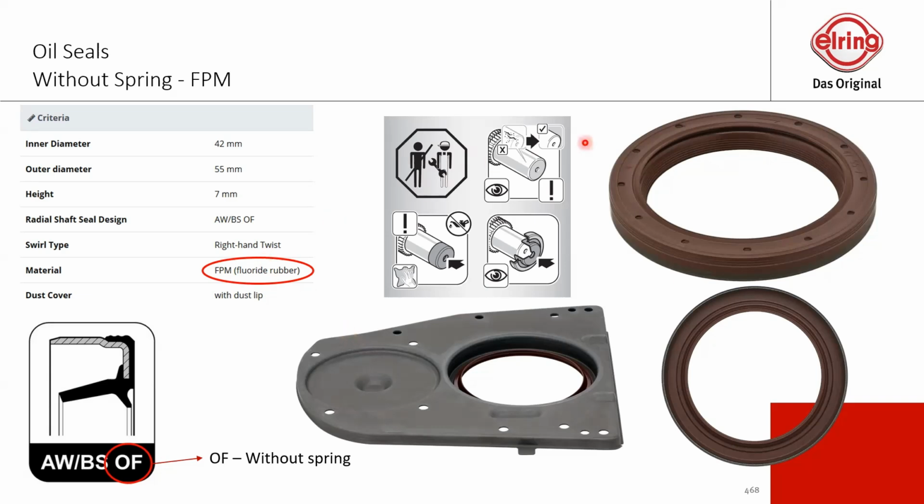If you check out the instruction manual, it's also not recommended to use any kind of oil during the installation because this oil seal is coming slightly oiled. If you touch this, you can feel it. So it's not necessary to add more oil on it. In this case, you don't have to do it, and you do not have to wait the 4 hours. And this kind of ring is nowadays used in more and more modern engines. So this is the benefit of it.